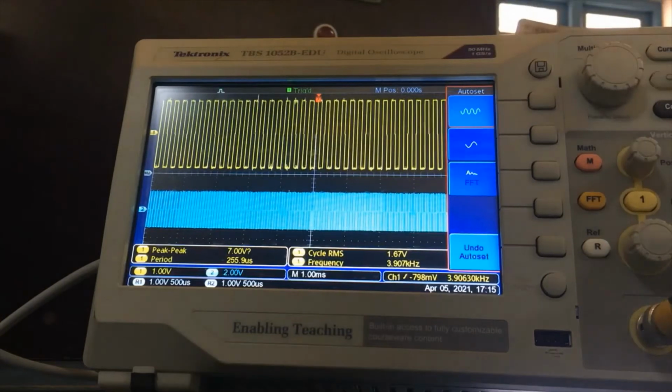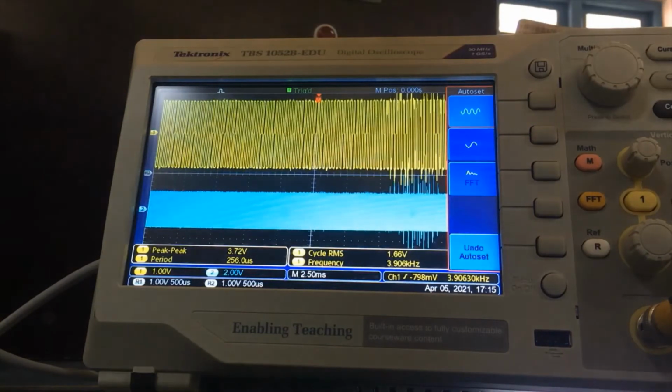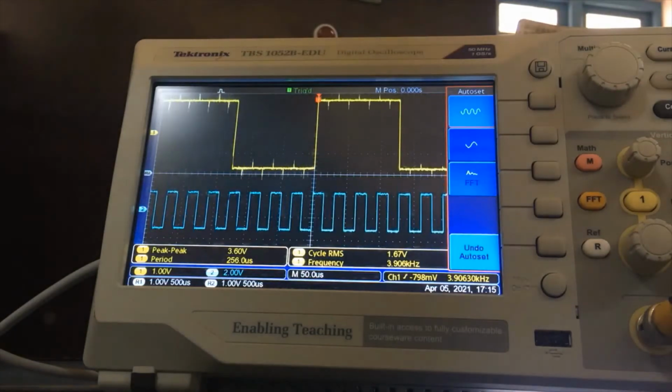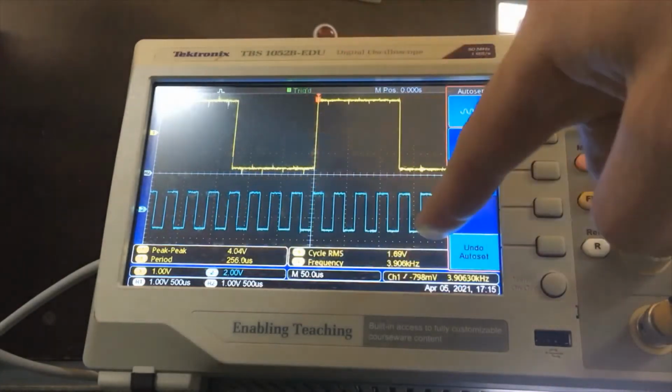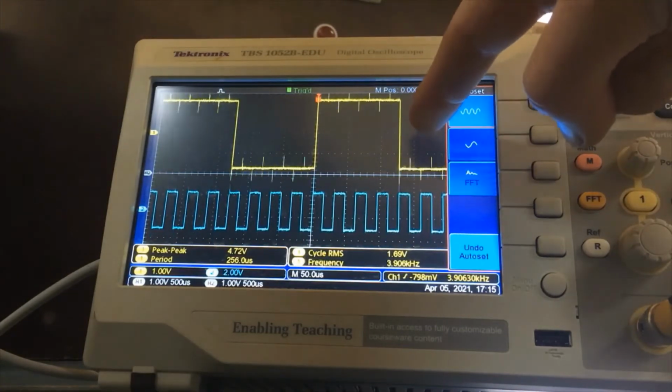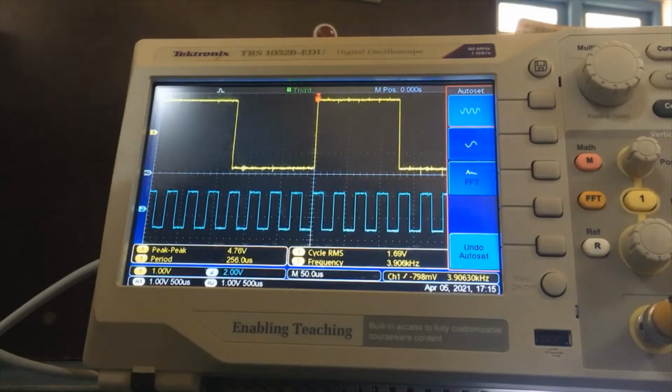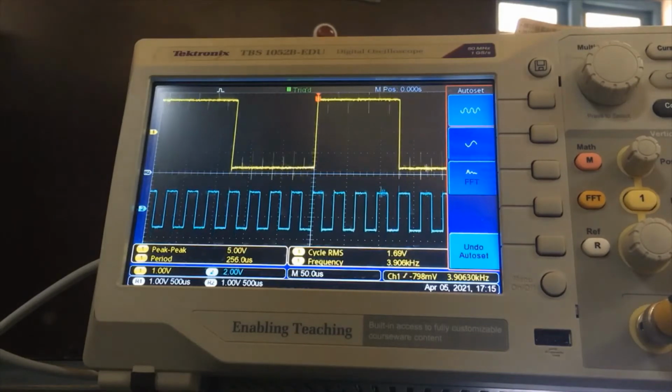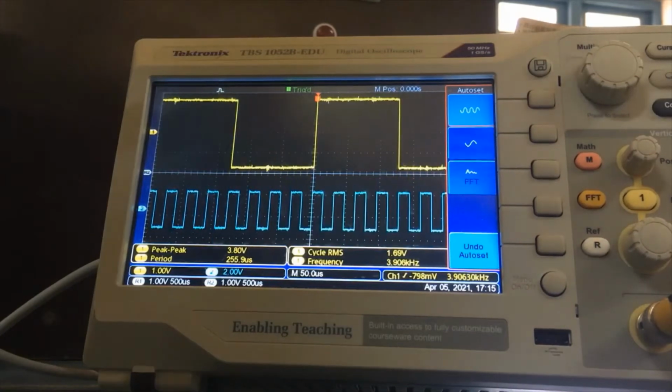That is because, if we reduce the time per amplitude, it will be more clear. Yes, as you can see, 8 times faster parallel to serial conversion than the sampling of the signal. That is essentially, these are the clocks only. This is because your serial data would be 8 times faster than the parallel data, because we are sending the bits now one by one, ones and zeros, instead of sending the sampled values parallelly, right? So this is the conversion.